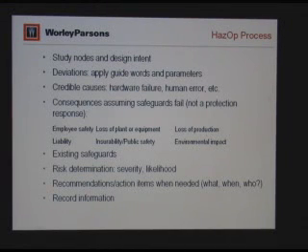So after considering the deviations from the design intention, we need to find out the credible causes. What can cause the deviation? Either a hardware failure or human error, which mostly will be operator error, and the consequences from this failure. And this is based on assuming the safeguards fail.